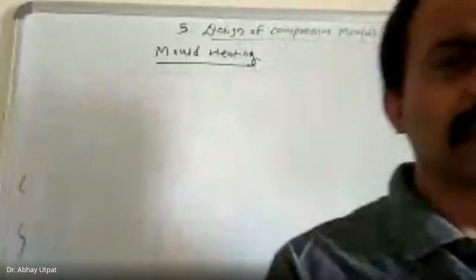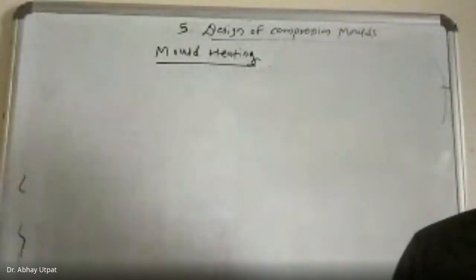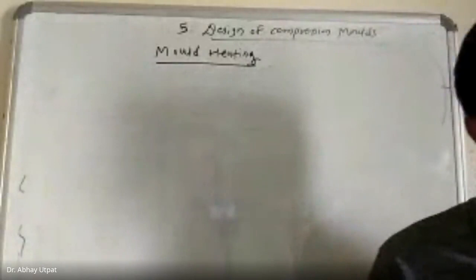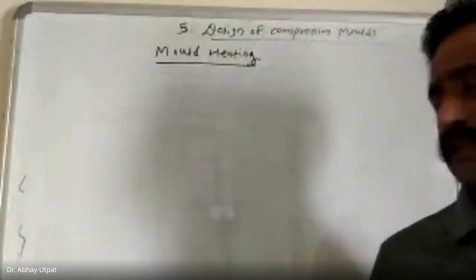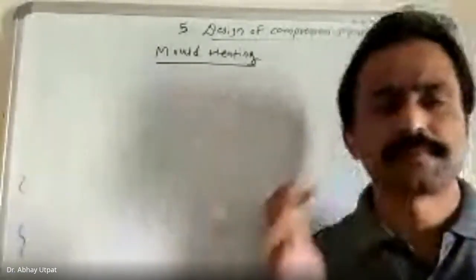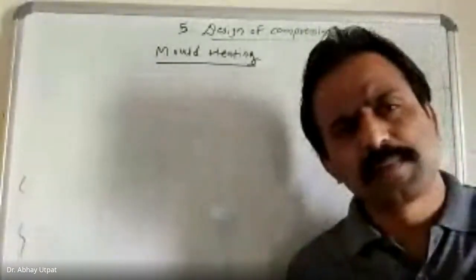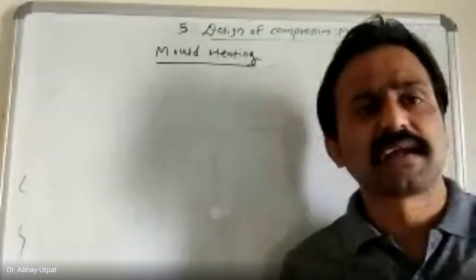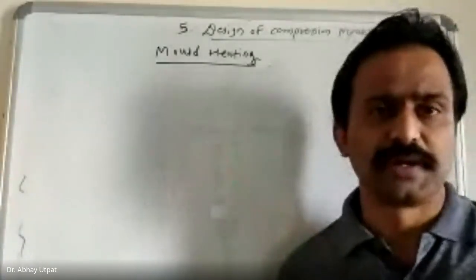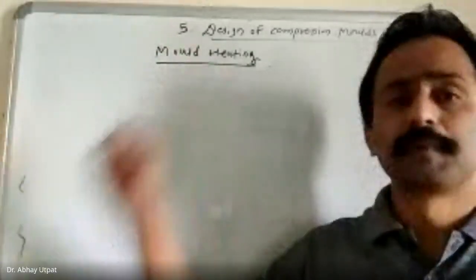There is a problem with this on-off control, and a problem of maintaining uniform temperature. Hence, oil or steam is preferably used, though oil and steam also have some disadvantages. Electric cartridge heaters also have some disadvantages. So an optimum solution is found out, and then the mold will be heated.